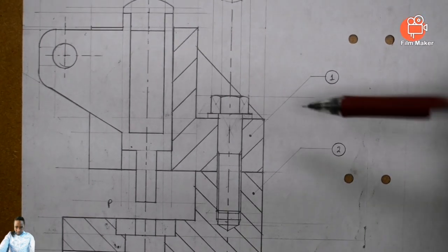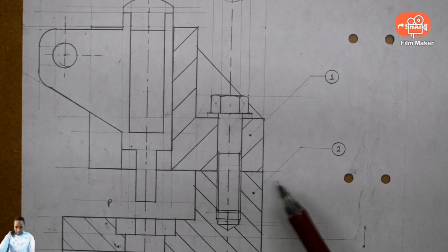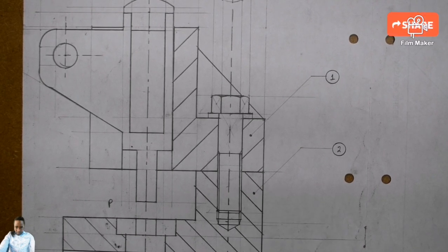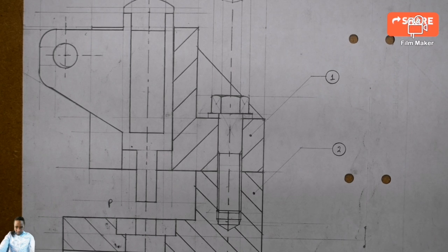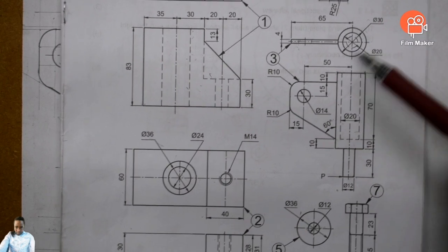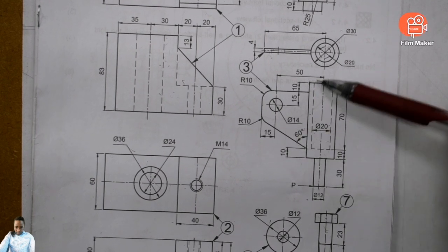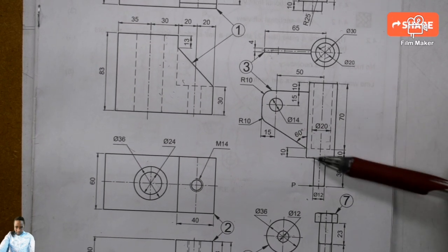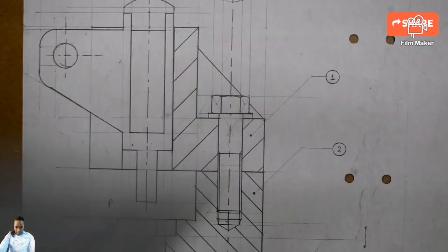So the moment I see these 1, 2, 3 and so on, I will have to expect even the hatches, which are 2 different parts. You see, the hatches are different in terms of their direction and in terms of their spacing. You understand? So where is your item 3? Which is this one. Okay. Item 3, we said from here till there disappears, from there to there disappears. Then this one is going to change to dark, because we cut to expose the inside view.